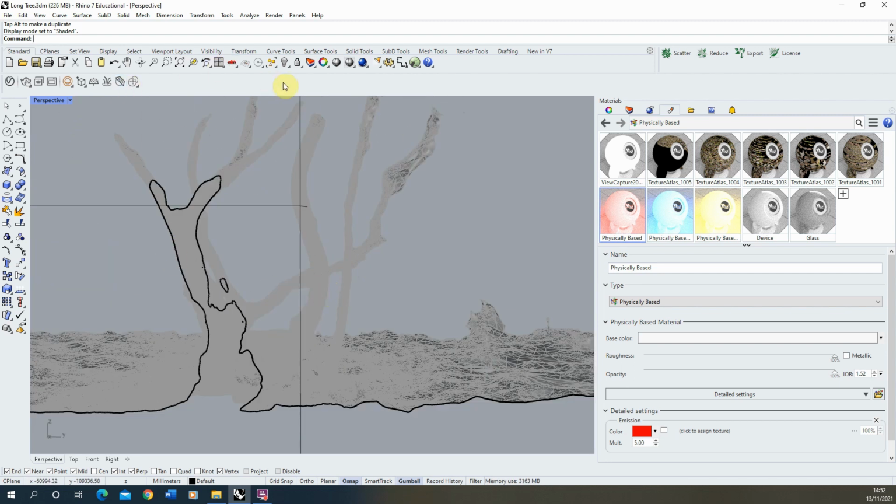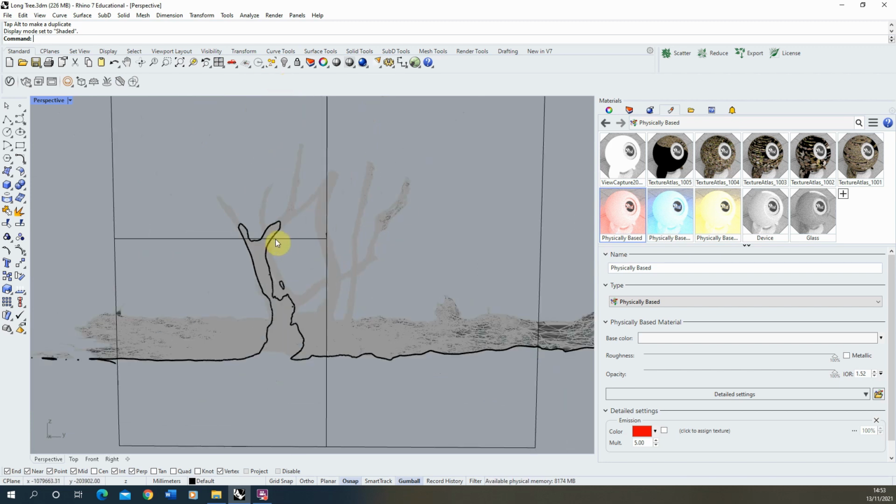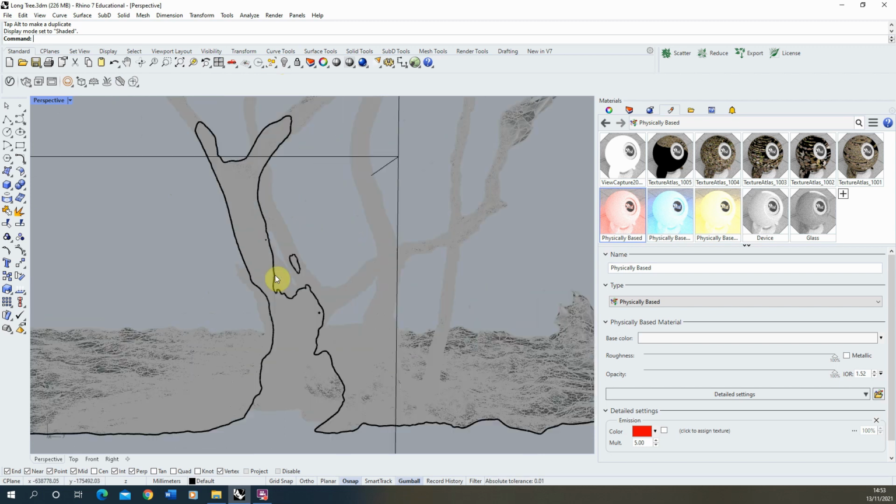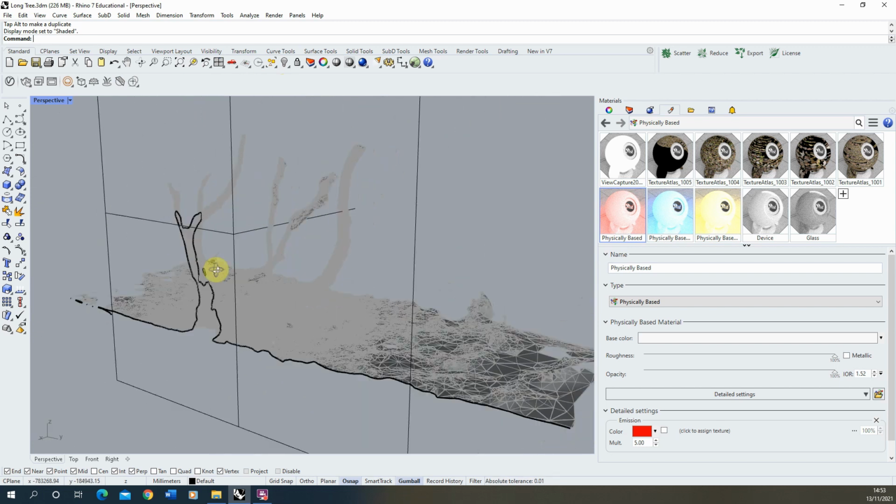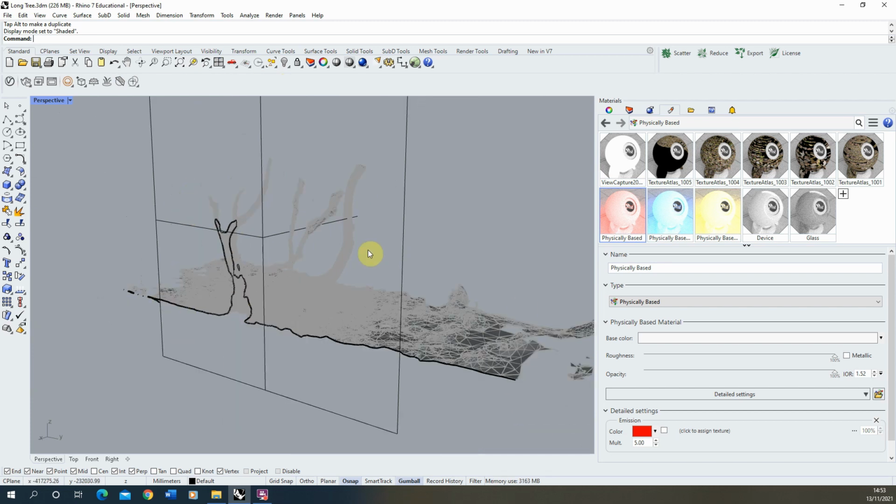So I'd recommend against using Make2Ds with these particular meshes because of that really intense tidy up work you get with them. What you can do, however, is we can still cut our section line from this, and we can get that as a nice piece of line work to use as the base of this drawing.